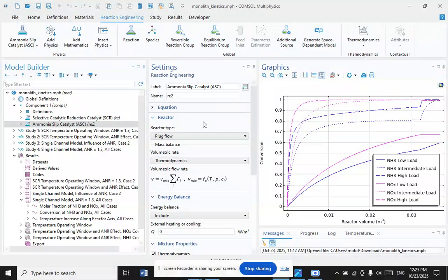And here you can see that it has been listed major commercial and potential attractive applications. Monoliths are the state-of-the-art reactors in many practical applications in environmental catalysis because of the low pressure drops at higher flow rates, the dust tolerance, etc. And what are the recommended subjects?